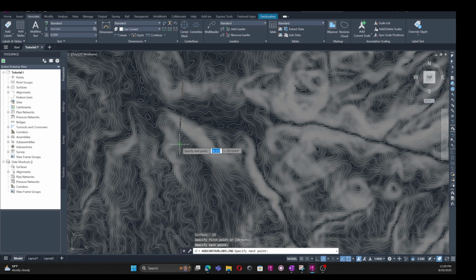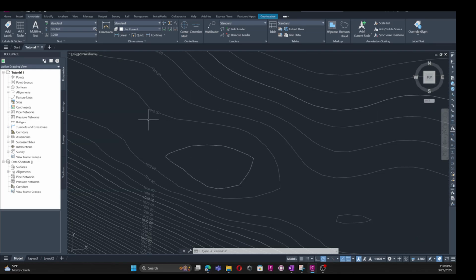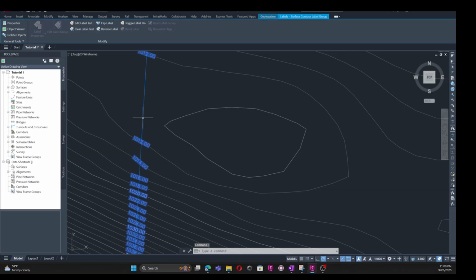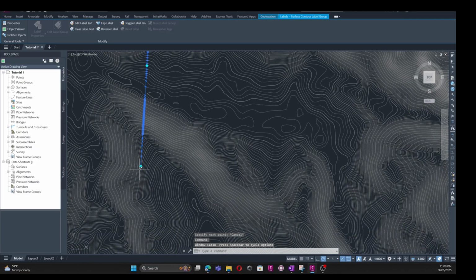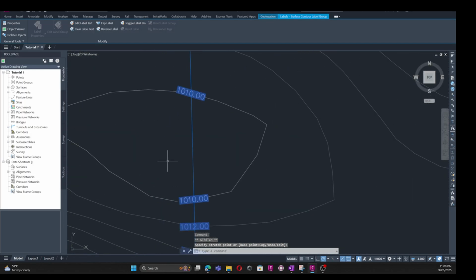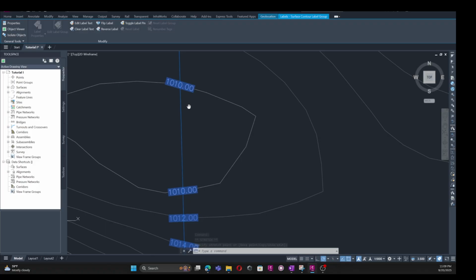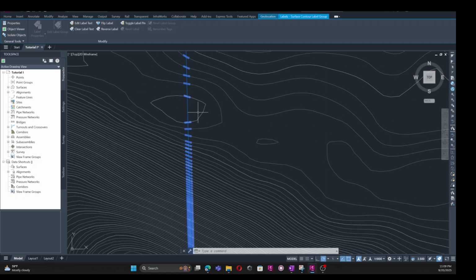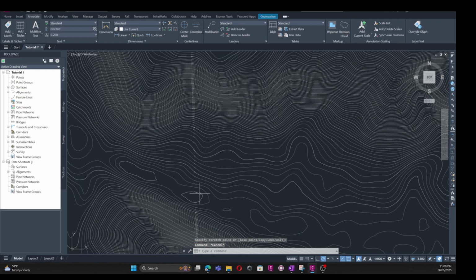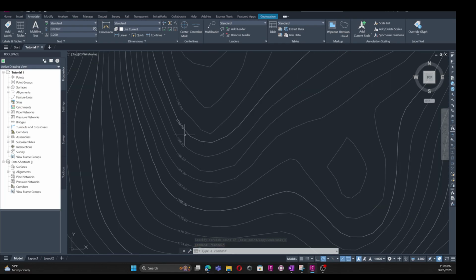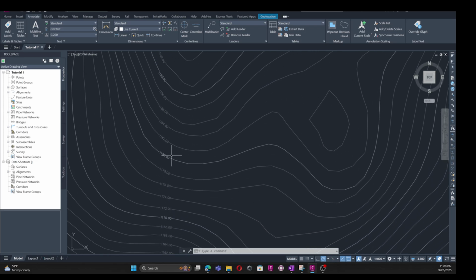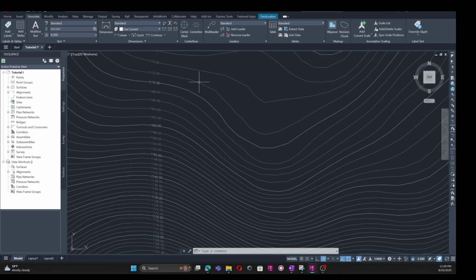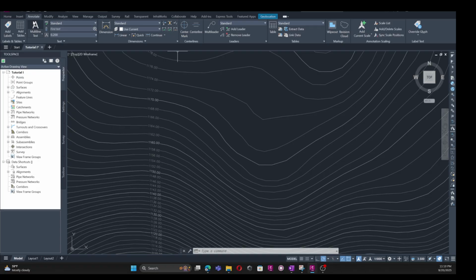This is my proposed dam location, so the minimum value is 1010 meters above sea level, and the maximum continues, but as per my previous assessment, an appropriate dam crest level could be 1170. So I will mark that point.